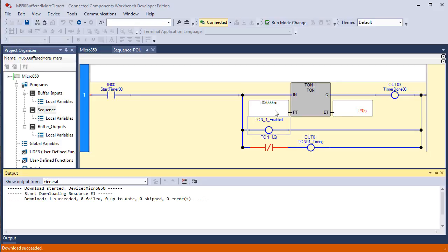I'm going to leave this in here because it's not hurting anything. Notice that I did not use up one of my precious few output indicators attached to outputs for this. I just used a bit in memory. And you'll notice when I turn input 0 on, enable goes on right away along with timer timing. Now the reason you see a little delay between enabled and timer timing is that is just the way the Logix read, and then the screen is updated. See, there they went on together. So it has everything to do with the synchronization of the video card in your computer and your screen.